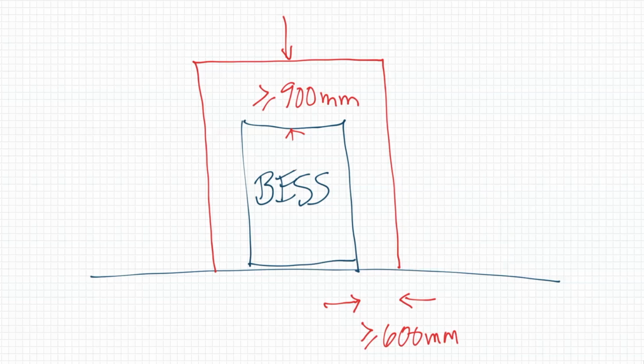That exclusion zone is defined in the standard as the area in which you cannot have equipment not associated with the battery energy system, or BESS. It's also the extent of the fire protection requirements, whether that's cement sheeting, concrete block, terracotta tile or brick. That area is the minimum you need to have that fire protection against the spread of fire barrier established. So in practice, I've seen people use compressed cement sheeting, apply that to the wall first, and then put their BESS or battery system against it.